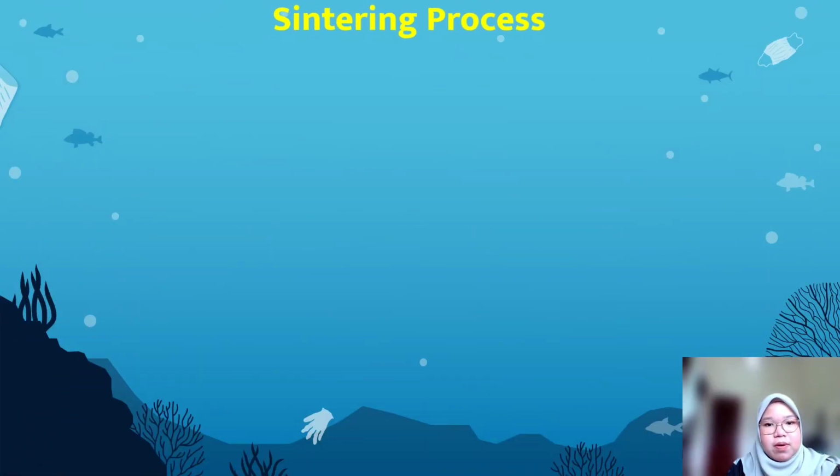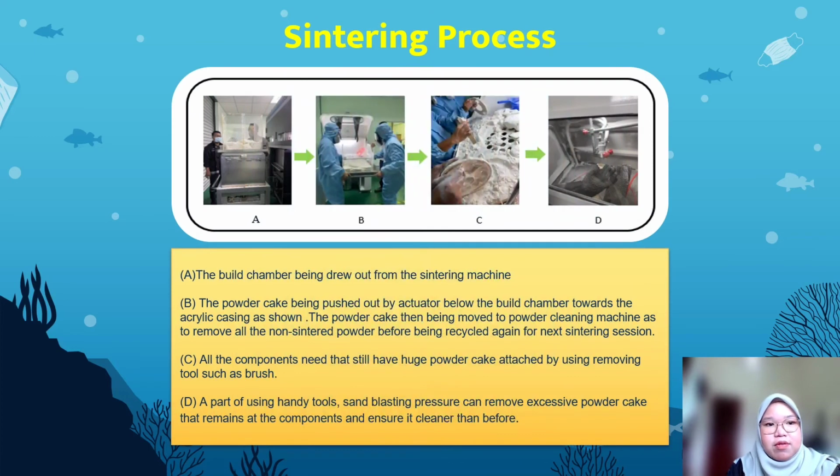Now I will explain about the sintering process. For the pre-processing stage, there are 4 steps, which begin with measuring the weight of the material based on a calculation of the height defined by the Farsoon SLS software, Farsoon All-Star TM Open platform interface with a 400 mm x 400 mm x 450 mm feeder chamber size. The weight required for the FS3200PA powder to fill it up is about 60 kg of powder.